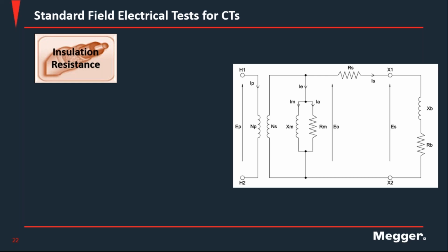voltage on the secondary. If you account for that, you need to perform on the Rogowski tests like ratio, polarity, and phase deviation, much like you would do on a regular inductive transformer. However, on the Rogowski, there's no saturation, so you wouldn't be performing any saturation tests.